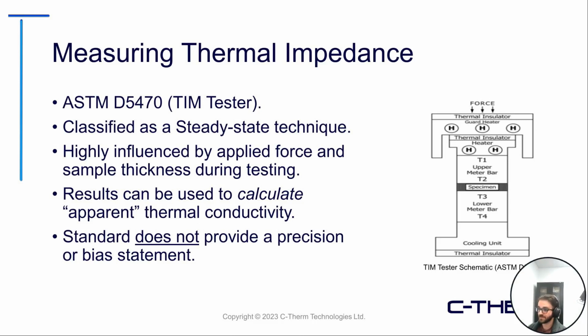One of the things to note about TIM testers, if you have experience with them, is that they're highly influenced by the applied force and the sample thickness resulting during the testing. So these are two factors that need to be controlled and well understood during the measurement. The results can be used to calculate the apparent thermal conductivity. This is the verbiage pulled from the standard. Again, you're taking one measurement and then converting it, so it's not a direct measurement of thermal conductivity, but it does provide a means of getting you that value.